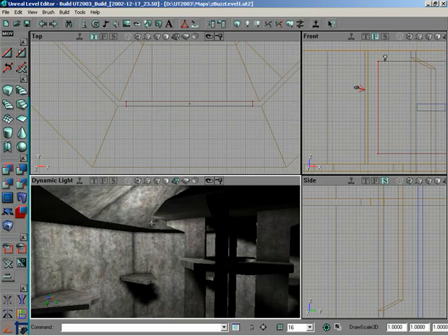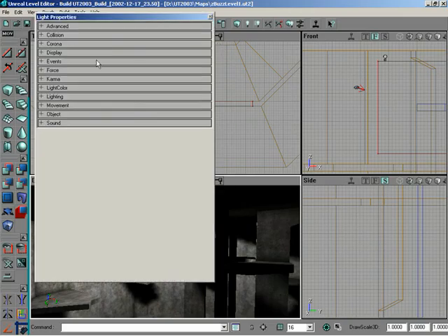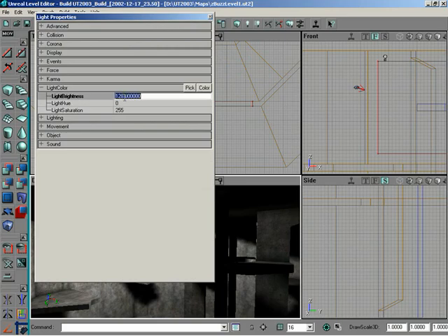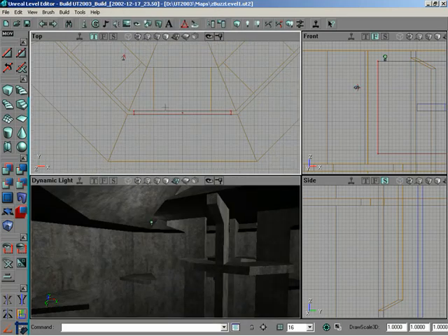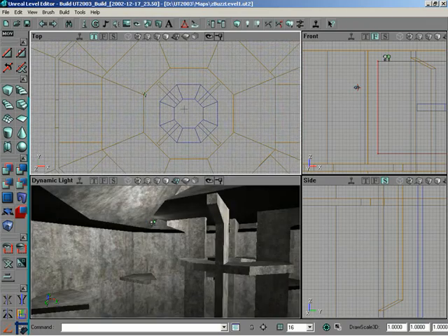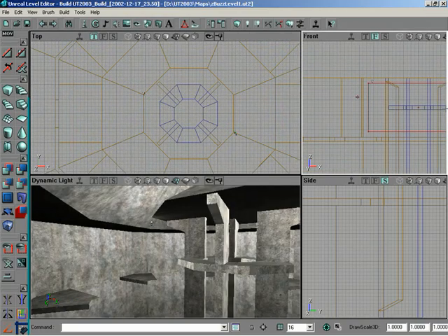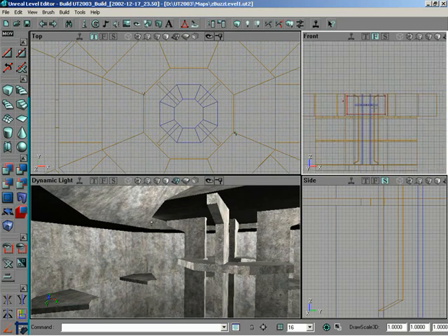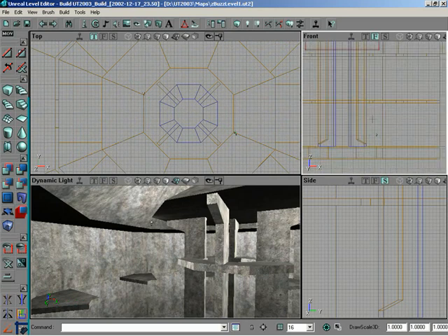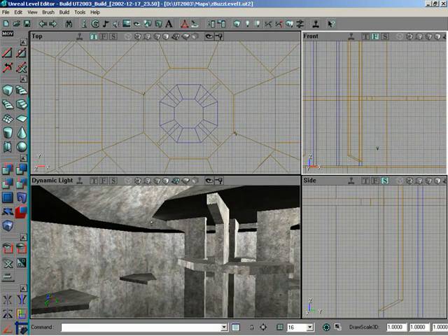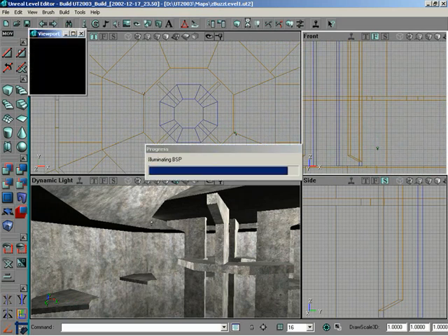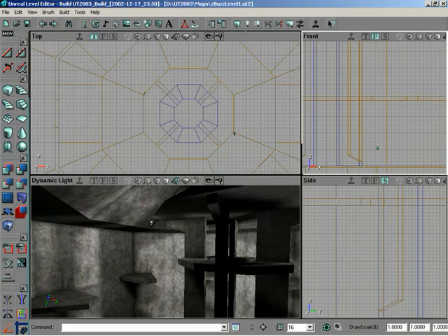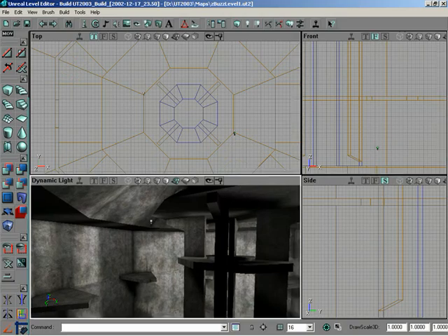Okay, I'll take this first light and drop its brightness by half, and then I'll duplicate it 2 more times. So dim it down a little. Let me find it in the top view. Control W, drag it to the other corner of the top. Control W again. Then from a front view, let me drag that down almost to the ground, maybe just above that bottom pillar there. So that way we'll have illumination from the bottom as well. And I'll go ahead and rebuild lighting. Okay. All right, so yeah, that's a lot better, a lot easier to see what's going on.